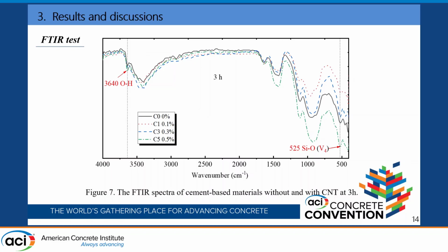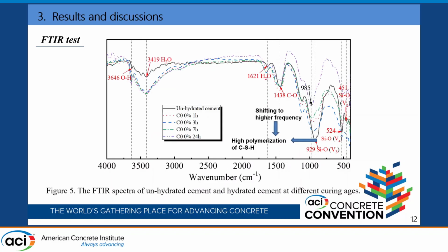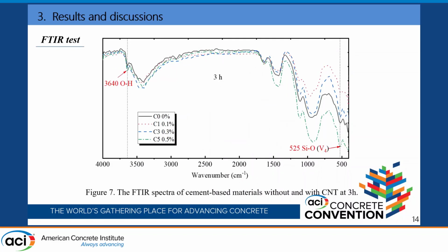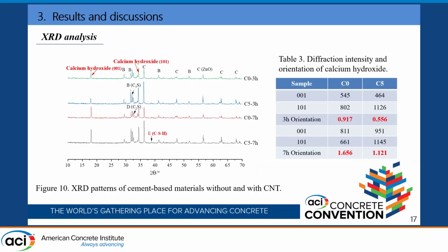And this I had shown earlier, but in the wrong place because there was no CNT. But we had observed that this peak is moved, the frequency is increased when we have CNT, and I will come back to that later on as far as the importance of this is concerned. Then I want to skip to the results of the XRD curve. Again, there are no new peaks, so addition of CNT doesn't really change the hydration product.